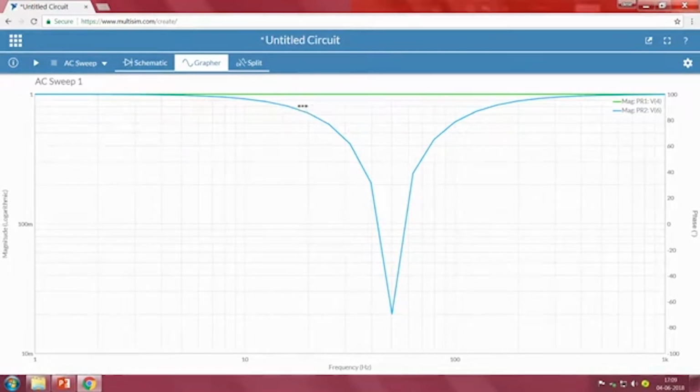So, when you see the valley, it is very narrow, that is why this is called a narrow band filter too. So, very narrowly we can cut down one particular frequency. The reason is that we are looking to eliminate or remove only the 50 hertz noise, and other things we do not have to remove.